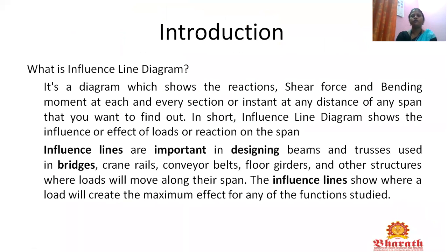It's a diagram that shows the reaction, shear force and bending moment at each and every section, or at any distance of the span that you want to find out. So in short, an influence line shows the influence or the effects of loads on the reaction of a span.